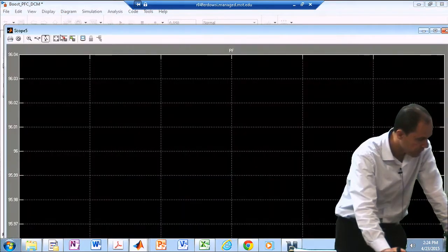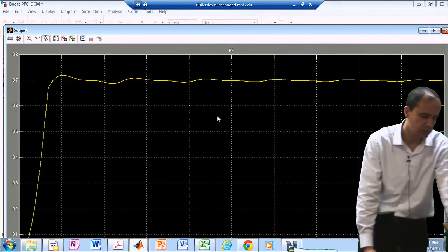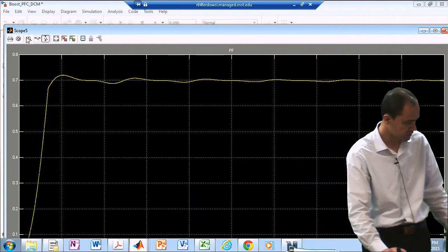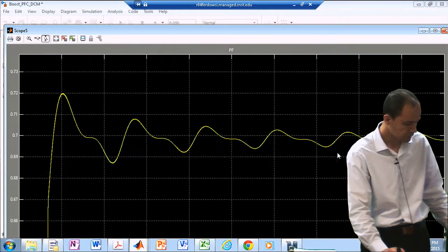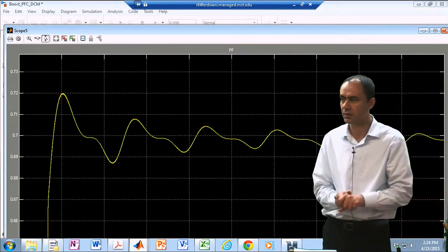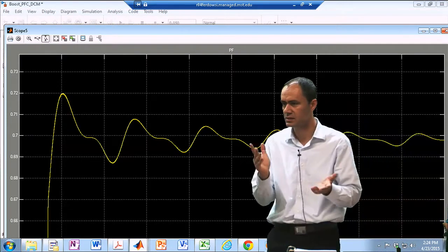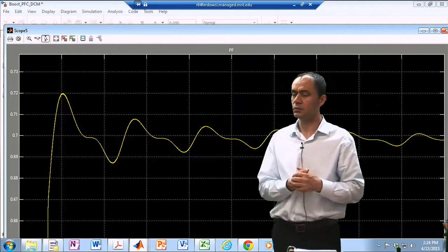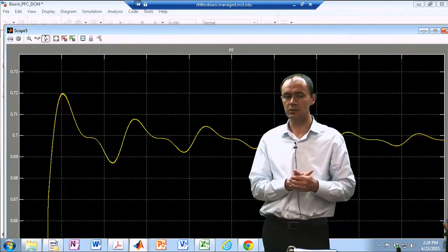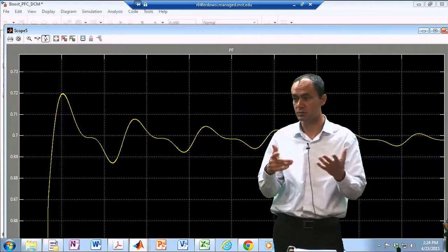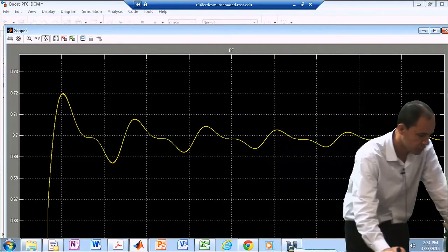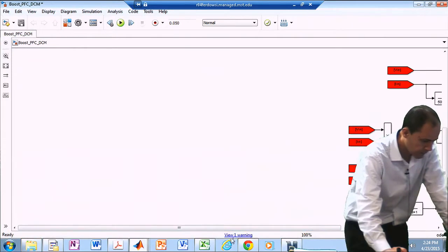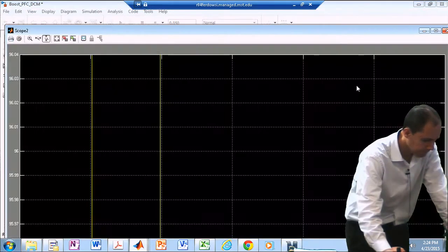So looking at the power factor, obviously my calculation is not absolutely accurate because of the low-pass filters that I have used. But it gives you a rough estimate: our power factor is about 70%, maybe 68% or something like that. So not bad, because if I take this boost out of the way, my power factor might be as low as maybe 40%, because it's just a bridge rectifier with a very distorted current waveform. Okay, let's take a look at this one now.